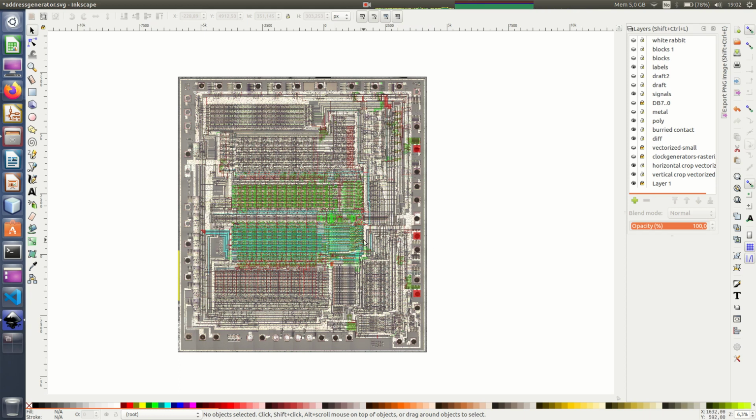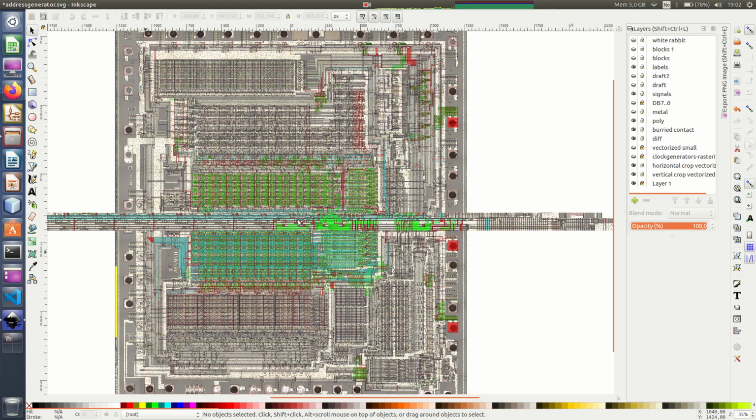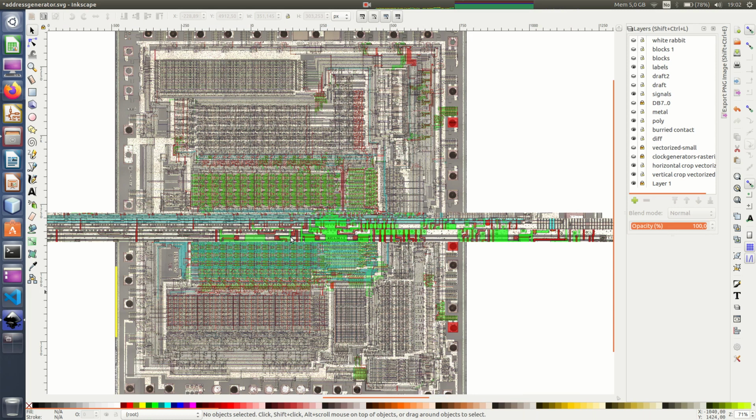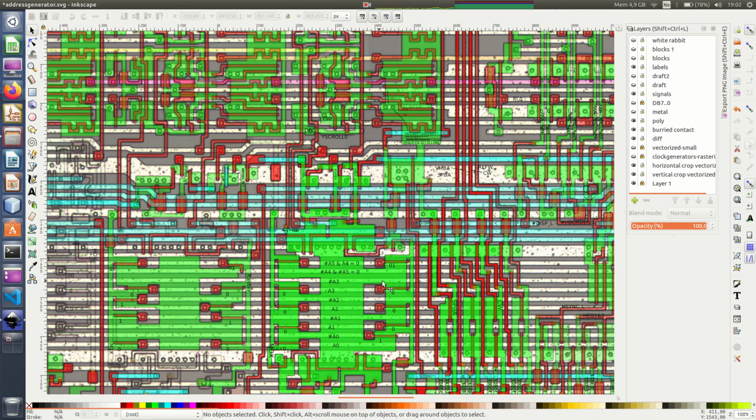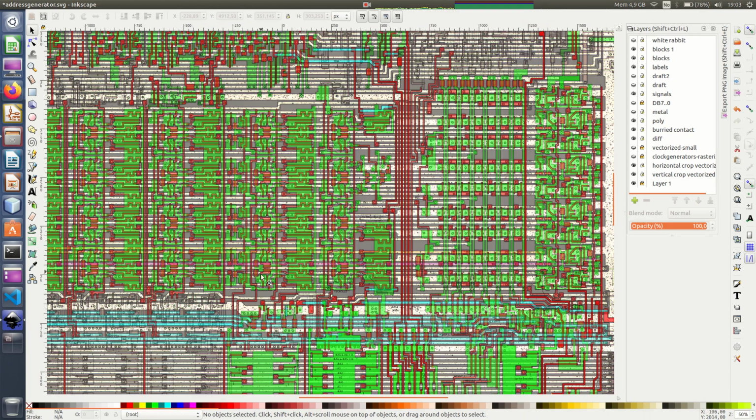The second thing I did was finding out that this must be some kind of address decoder, and I figured out that if I put numbers on it, I actually got a match on which address was what. So that's another file, but anyway, like this one, and this one is another register. It has a comparator. There are data lines coming in on the register. There are read and write signals.